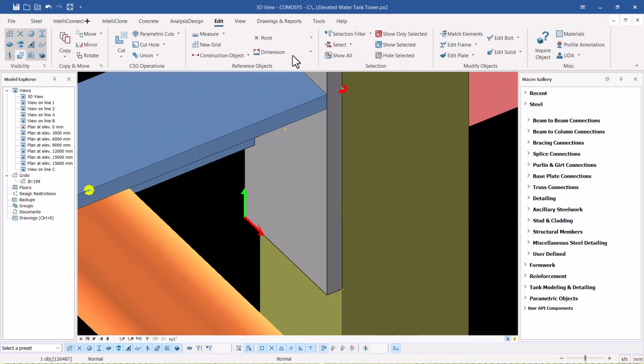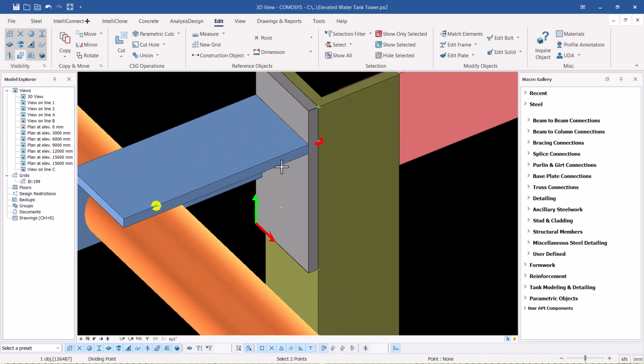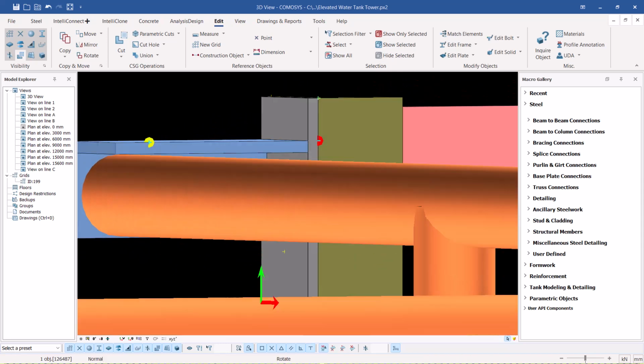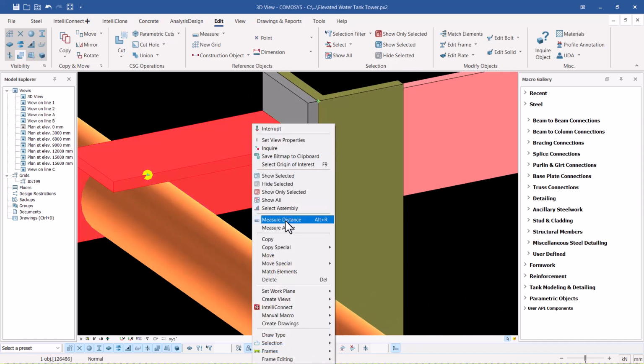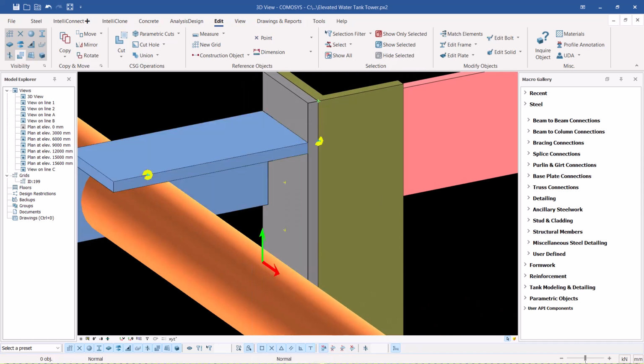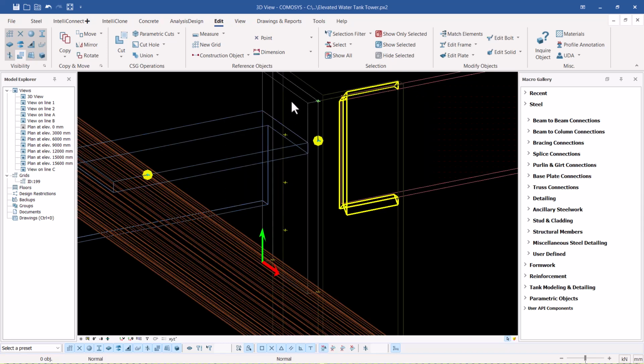If I come back here again and create a midpoint between that midpoint and this edge, I'll have a point there and a point somewhere here. So let me use the same point to create a midpoint on top there, and that is not visible. What we can do is click on this and hide, or press Control Alt D, so that we can see this point here.